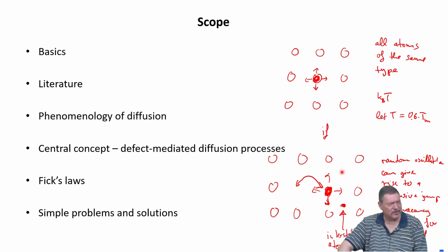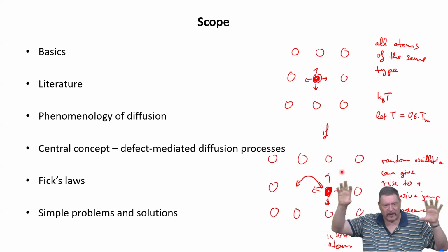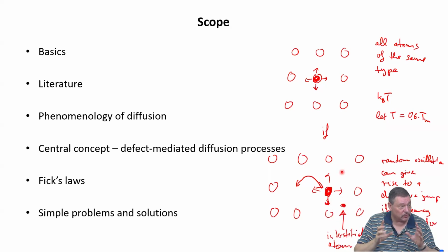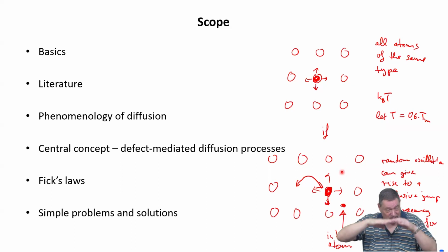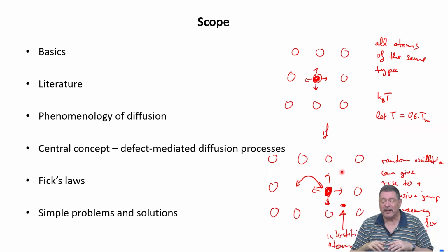Yeah, it is correct, but the reason is that interstitial diffusion doesn't need a vehicle, because the interstitial lattice is always there. So there are free spaces provided by the lattice itself, and it needs to push through. It's smaller, so that's quicker. That's reducing the activation barrier, absolutely correct. And additionally, and this is the larger part of why it's faster, the activation energy to create a vacancy nearby is not necessary, because you don't need a vacancy. So there are two aspects why this activation enthalpy is lower, and this is why interstitial diffusion is always much faster than substitutional diffusion.